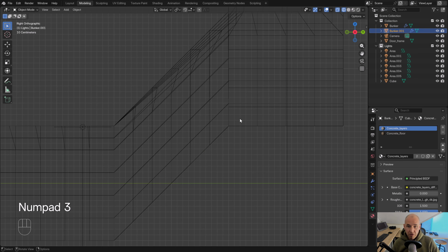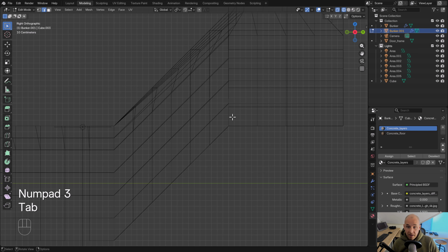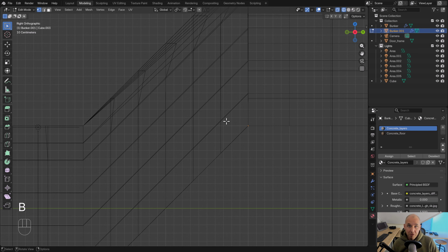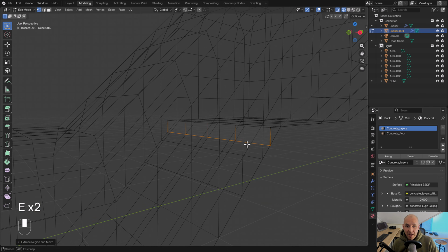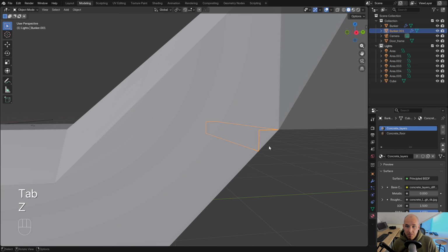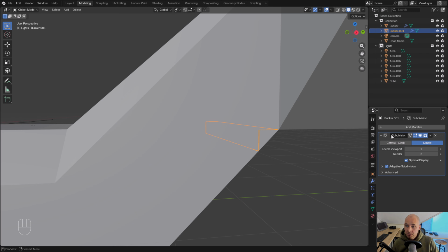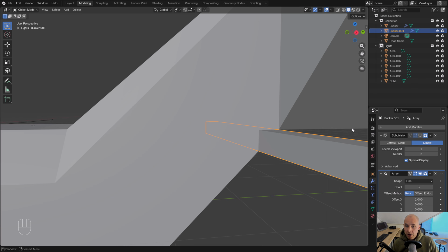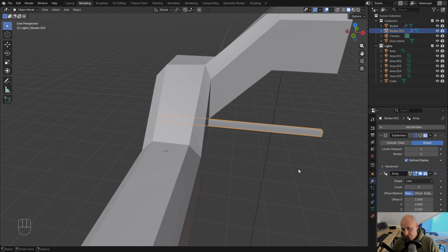You go to the side view, press 3, press 1. So now in the edit mode. You're still following me, I hope. Press E and E again. So you have this rectangle shape. We're going to do something fun. Go to the modify tab. You can keep this, just make it invisible and go to array. So it's arraying it to the right.